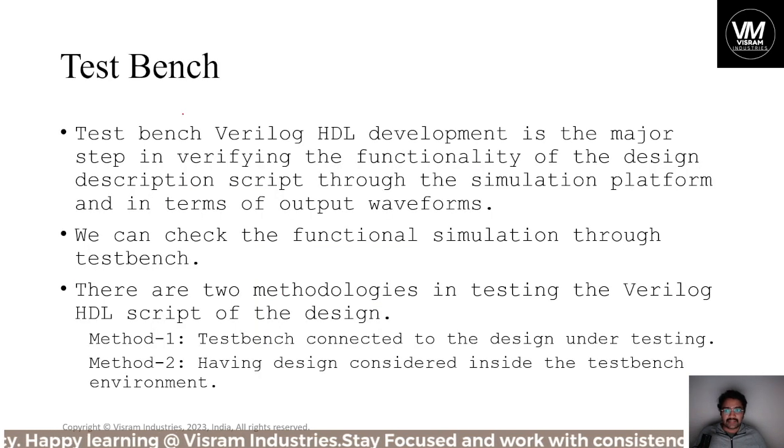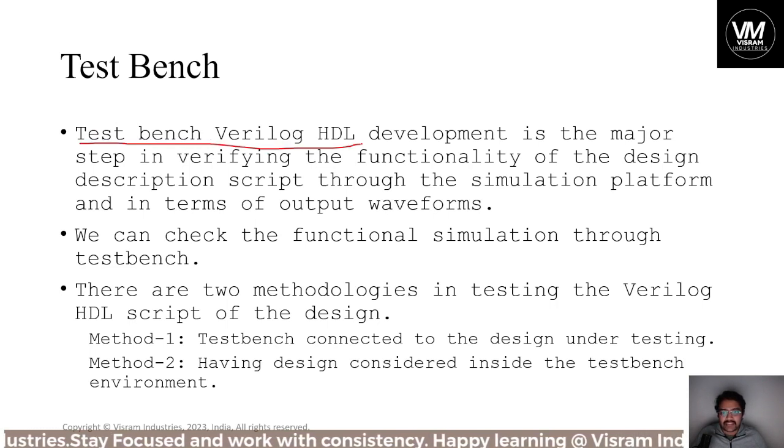Hence, let us start with what is test bench. I'll go through it line by line to explain what it actually means. When you go through the video again, you will be very familiar with this. Here, test bench of the Verilog HDL in the architecture development in the design of an FPGA. Test bench plays a simulation role where it is most important to check the functionality of the code that you have written. For example, you have designed something in Verilog HDL. You have a design.v file or design.vhdl file. For that, you need to check the functionality. How do you test that? You need to test it, right? For that verification, we will be checking with test bench.